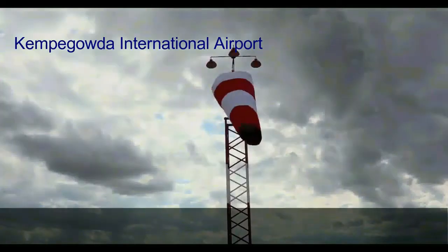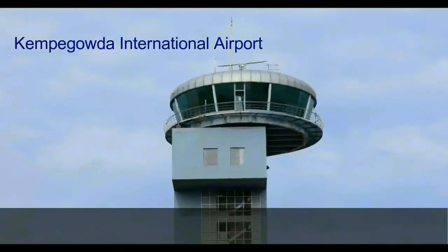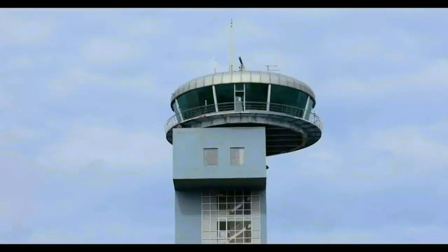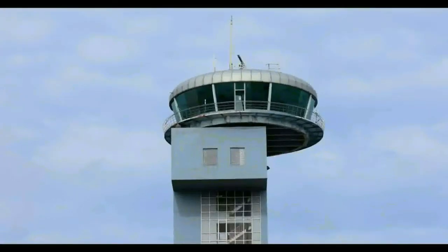Wind 020 at 8, visibility 4 miles with mist. Sky conditions scattered 1,600, ceiling broken 3,100 and broken 4,300. Temperature 20, dew point 19, altimeter 3005.